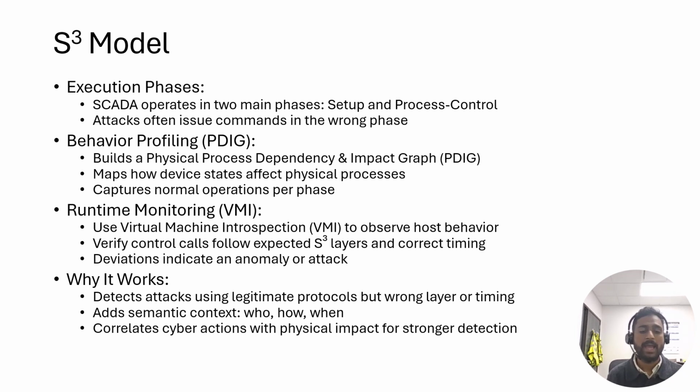So by adding semantic context to legitimate-looking protocols, like just simple read write commands, they're able to see who is sending this, when, what state of the process they're sending in, and even why, as process field states change. They're able to add context of who, how, and when. And this can help indicate a cyber event that may not otherwise be found by simply monitoring the traffic.